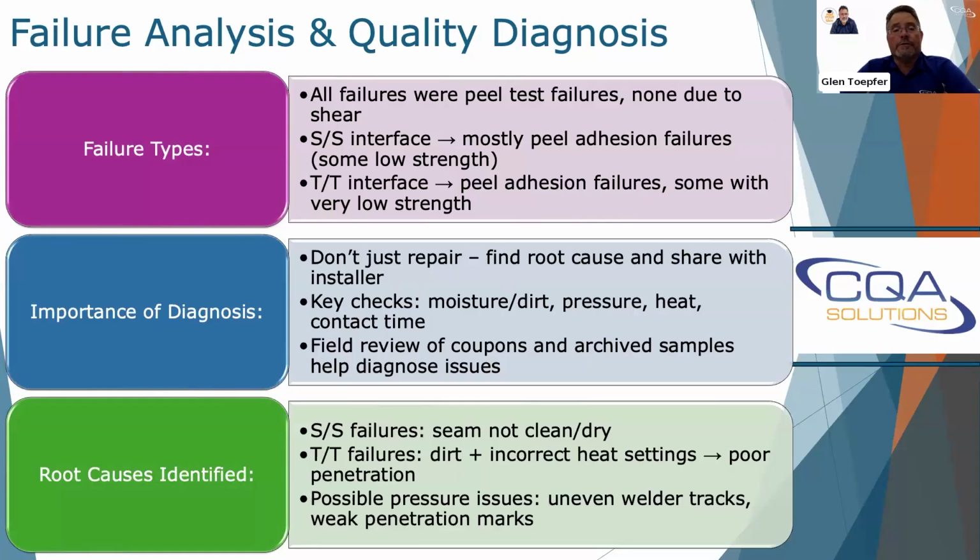Heat, speed, pressure, and moisture and dirt are common ones, but sometimes there are material issues as well. And then, obviously, dirt was a big one for smooth. If it wasn't dirt or cleaned, we had a lot fewer failures. Dirt seemed to be present quite a bit. Texture, a lot of times that's dirt. We'll get into dirt later. And then poor heat penetration.